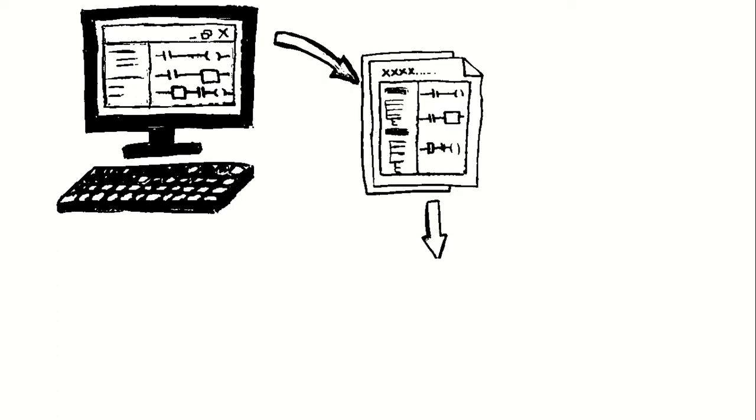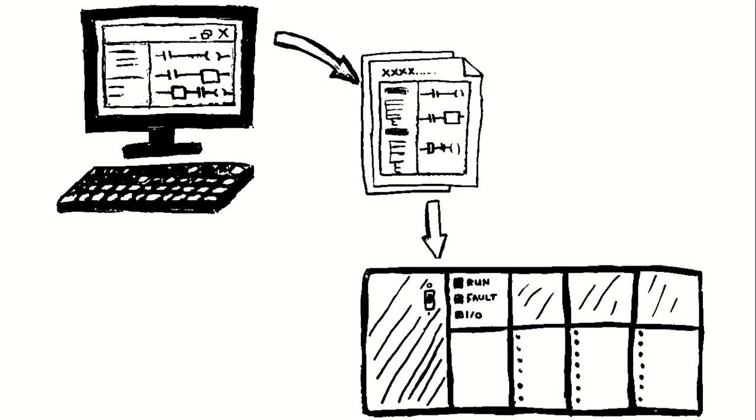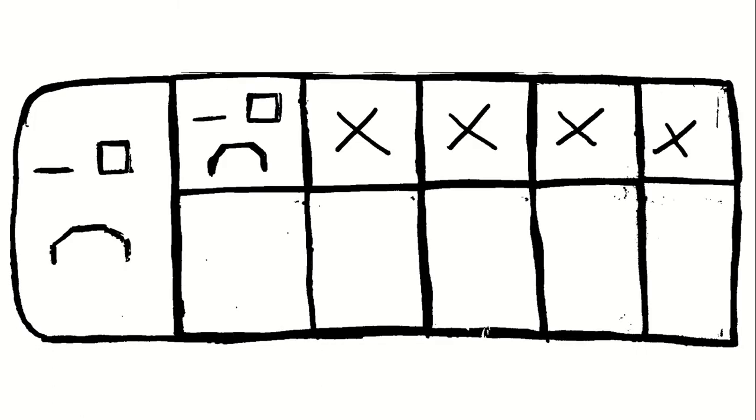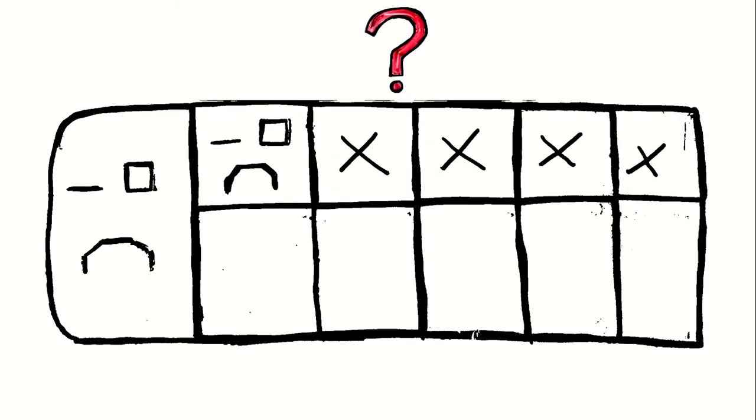When you work with controllers or smart systems, be it PLCs, microcontrollers, or field network masters, you must know that you need to start by downloading the configuration to these devices before you can start working on them. When you buy a PLC, it is just an expensive piece of hardware, and it doesn't even know that it's a PLC.